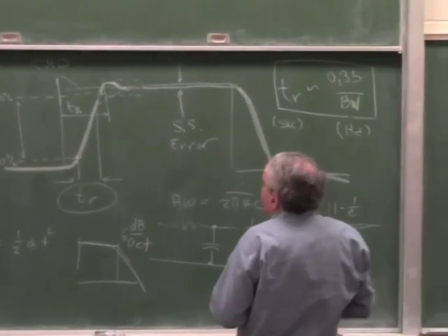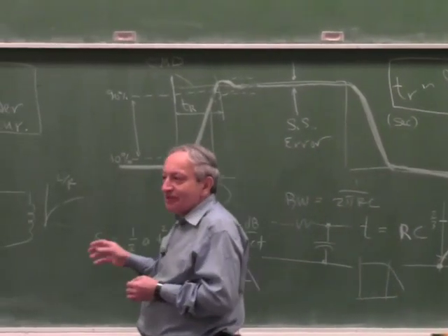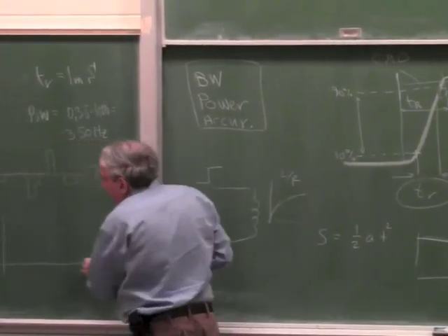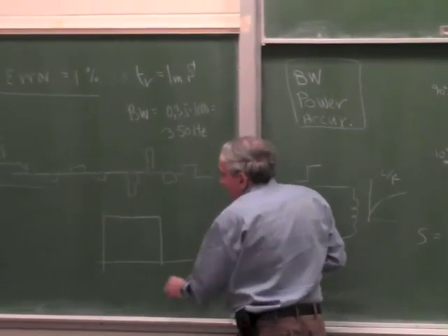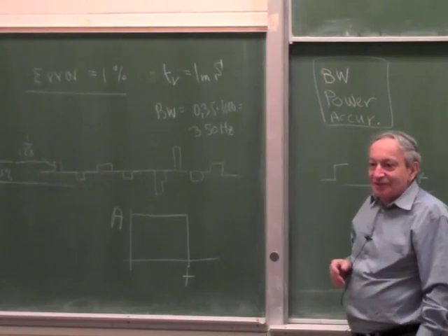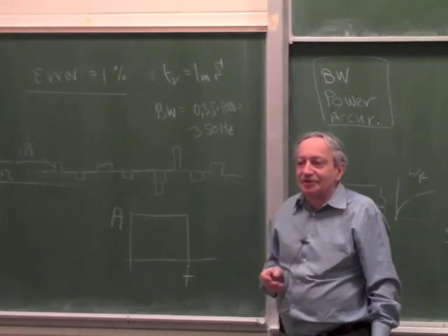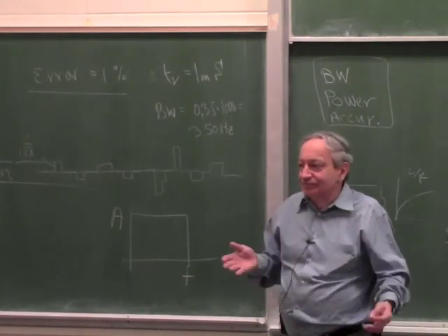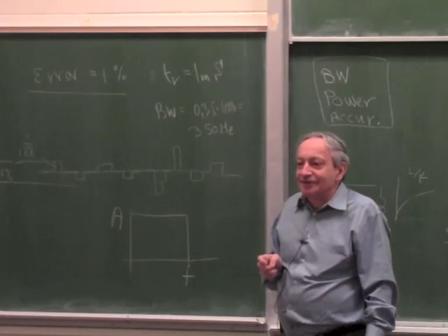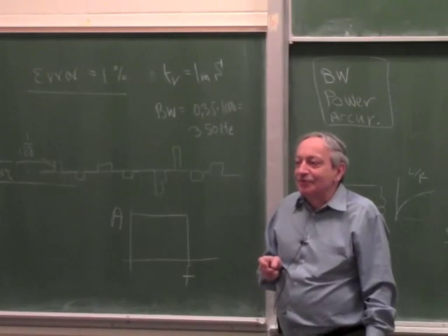I also want to remind you of this issue we dwelled a long time over, the choice of filters for servo systems. That's a very important thing, because in every servo system you need some filter, and I explained, and I hope you remember, that a filter which looks great on paper like this, if this is F and this is A, could actually be very bad for a servo system. Just to see if you really remember, can somebody remind us why this could be very bad for a servo system? We spent a whole week on that. You have sinc function? And what's wrong with that?